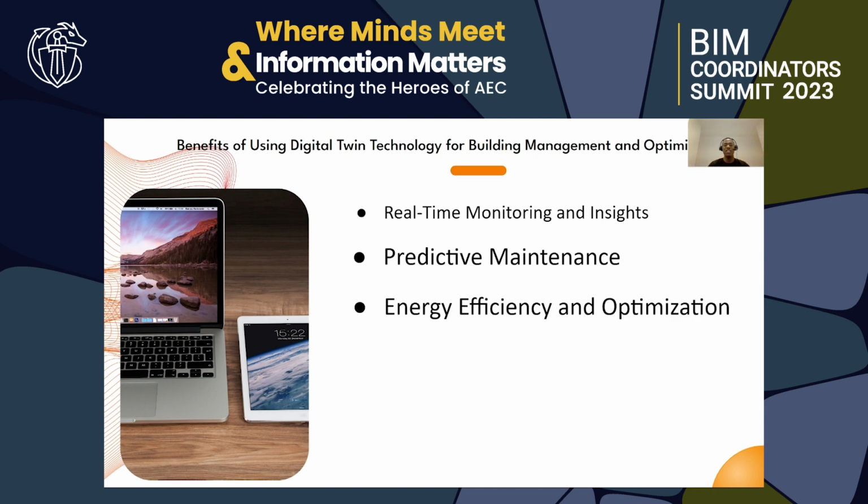The next benefit that digital twin brings is energy efficiency and optimization, because digital twins help to optimize energy usage by analyzing real-time data to identify areas of improvement in our buildings. This can be done by adjusting the cooling systems, heating systems, lighting systems, and ventilation systems dynamically.